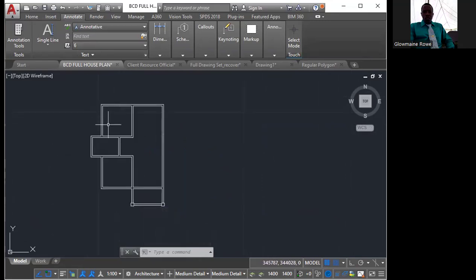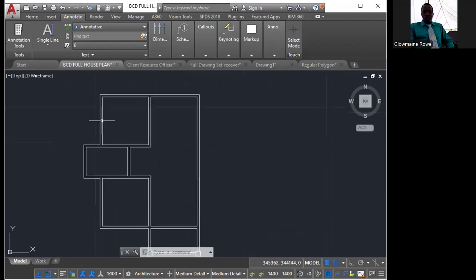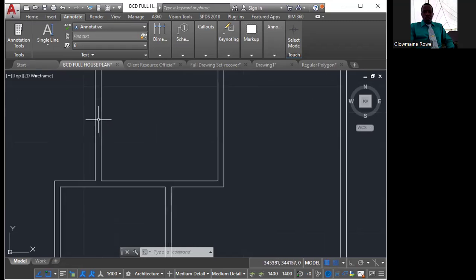As we said before, your foundation trench, and this is for strip foundation, will always be 3 times the width of your wall. So your wall is 150, your foundation trench is going to be 450. So we simply offset 150 on one side and 150 on the other side.